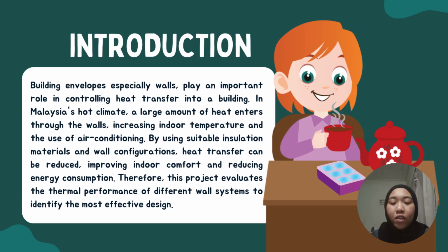So for the introduction, building envelopes, especially walls, play an important role of controlling heat transfer into a building. In Malaysia's hot climate, a large amount of heat enters through the wall, increasing indoor temperature and the use of air conditioning. By using suitable insulation materials and wall configuration, heat transfer can be reduced, improving indoor comfort and reducing energy consumption. Therefore, this project evaluates the thermal performance of different wall systems to identify the most effective design.